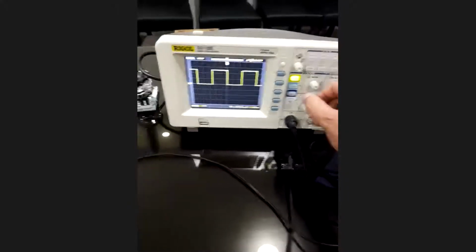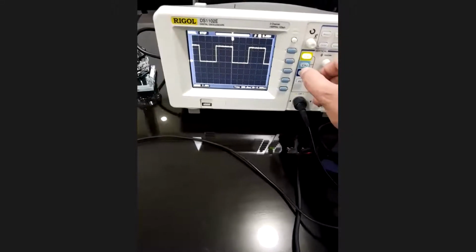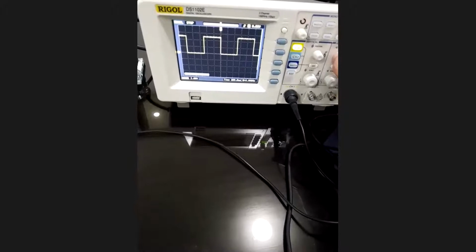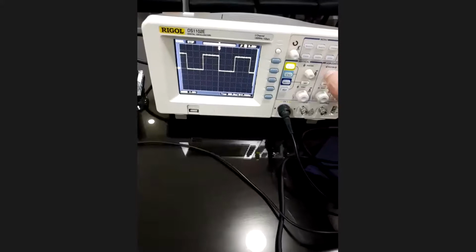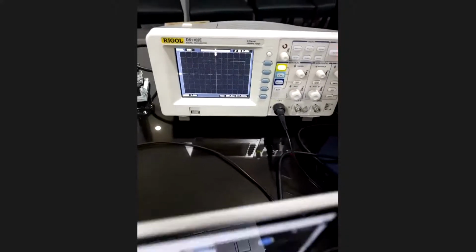So look at the time high. My square is 2 volts. The time is 200 milliseconds. Look, it is like 2.5 squares, right? So exactly high 500 milliseconds, low 500 milliseconds. Okay? This is the LED working.